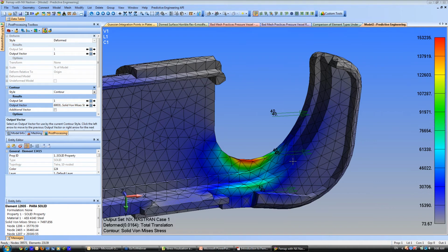Not a good outcome. At the end of the day, what did they do? Well, they remeasured everything, did some experimental work, and determined that the stapling load was around 10 pounds, not 40. The stapling load was 10. So then they said, well, let's just use 15 pounds for our QC load. And since it's a linear static analysis, you can scale the loads. So 15 over 40 is about 40%. And so instead of being 150, you're down to like 70 to 80,000, which is below the yield, and the part survives. You're all good to go.